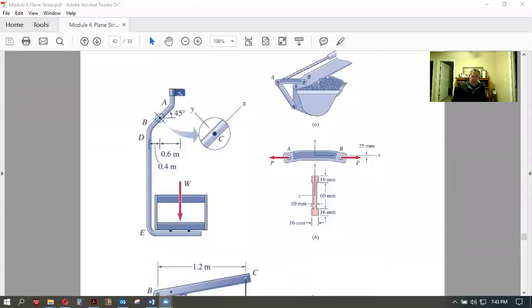In this case, where you've got a little bit more complex of a system, both simpler and more complex, the ski lift on the left here has a tube that then comes down, wraps around, and then the chair sits on top of that. Right? Well, when you look at certain portions of that tube, A, B, D, E, and how it wraps all the way around, you're going to have both some bending effects as well as shear effects and elongation types of effects to have to deal with.